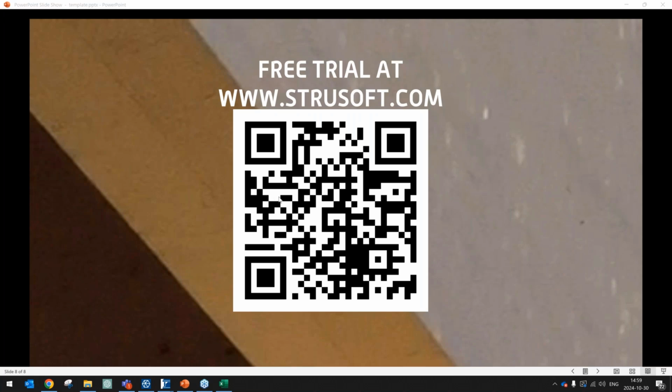Okay, I have one question over here. It says, is there anything known or required to calculate for deformation and stresses in the material due to changes in humidity in the panels? There is no more advanced model compared to the one presented in the Eurocode, which is basically the creep value.